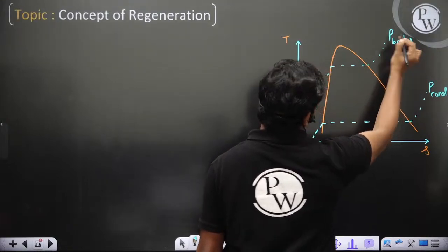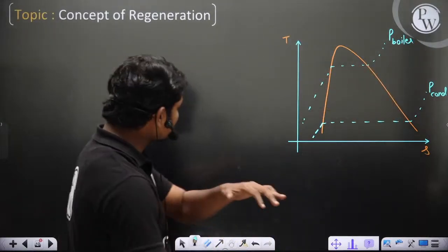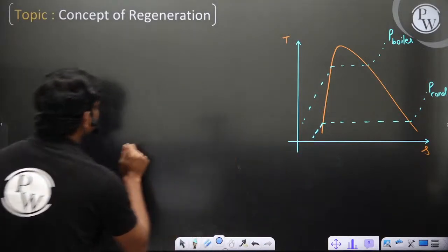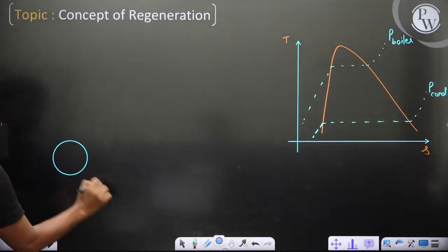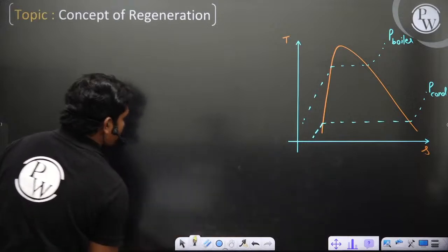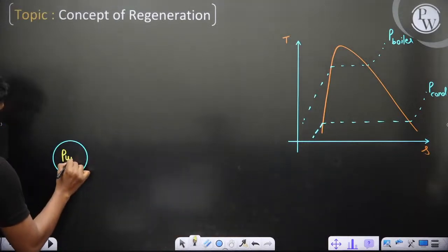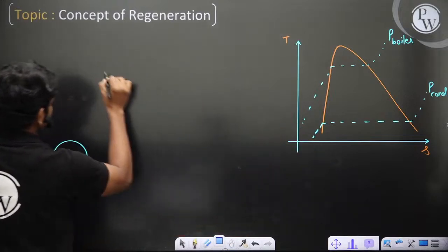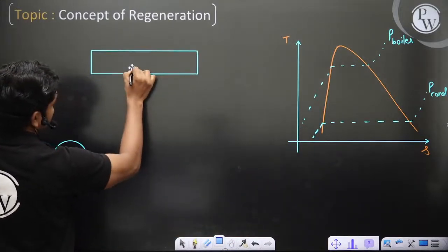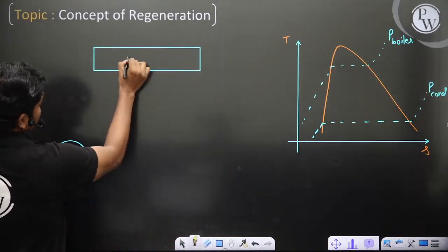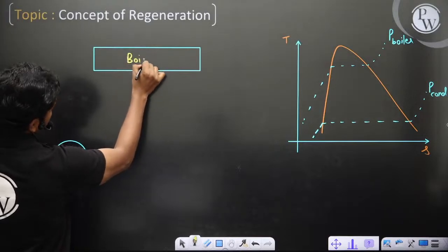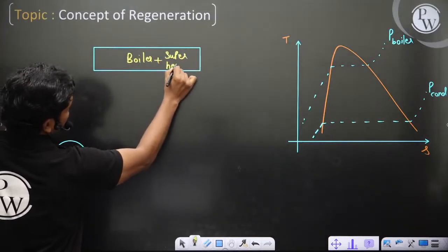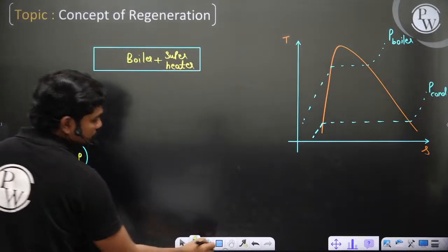Okay, so this is the boiler, and the actual cycle that you have here is the normal cycle. First I'm drawing the actual cycle. We have a pump, then you have some boiler plus superheater, of course. Normally we have understood we have to superheat the steam, superheater.